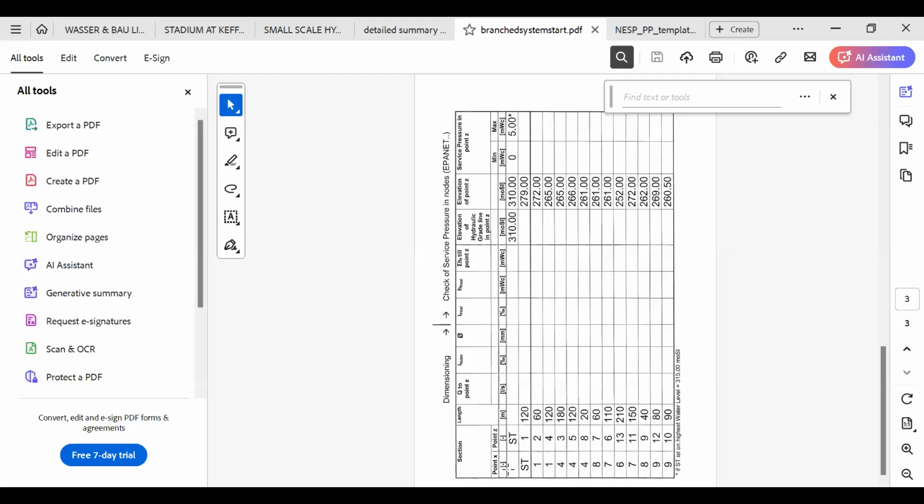So these 2 columns could be the XY coordinates and then the length between one coordinate and the other one, whatever parameter it is. But it is good for you to number it this way if it's a small design, so that you can name every pipe. So if the pipes are changing, you say pipe 2 is 100 mm, pipe 3 is 150, and so on. Even though it comes in terms of point to point, it's good that you name it to make sense. Remember, as I said, this is a standard international design. This is how it is done, irrespective of any country.